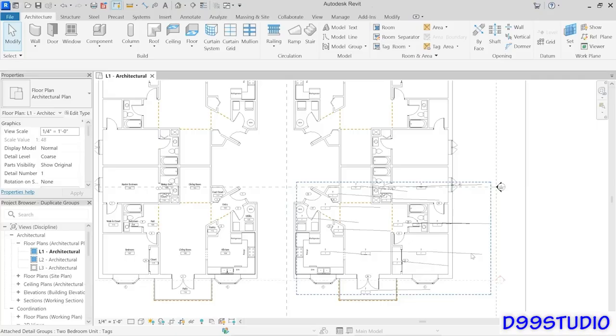But in general, what you need to know right now about room tags is that room tags get unhappy when they're outside of their parent room. To solve that, you can turn on the leader. Revit is trying to do this for us automatically, as you can see. All of the room tags have just sprouted these leaders. The trouble is when we did the move, it got confused over the position, and so the tags are still outside of their rooms somehow.